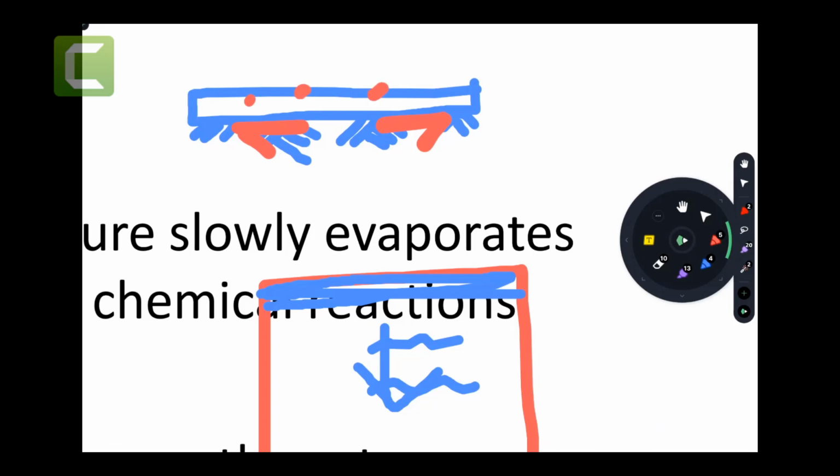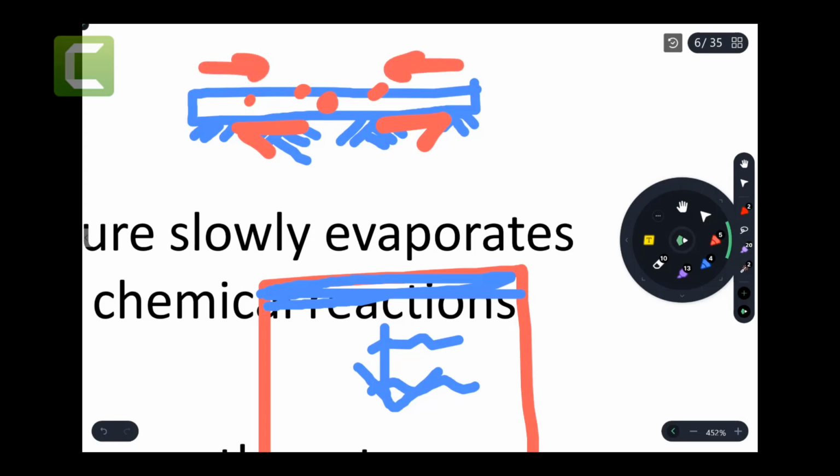Due to shrinkage, when this slab tries to shrink, it will try to move this way to the center of mass. But Mr. Soil will say no, he will resist that slide, those few millimeters or micromillimeters, whatever. And then the ugly cracks will start happening.